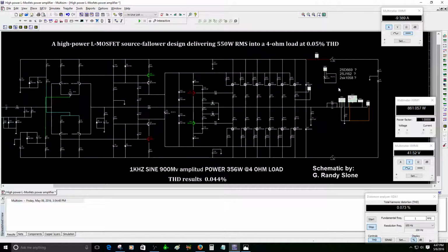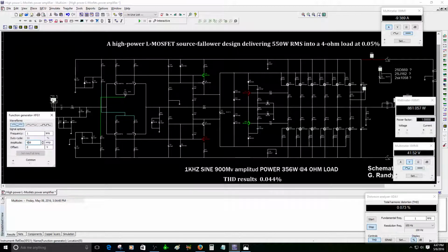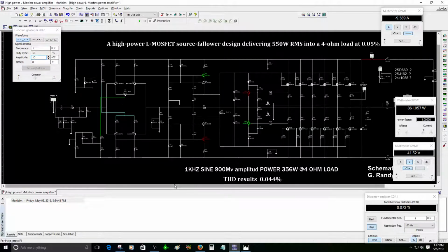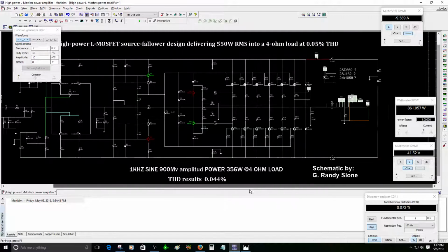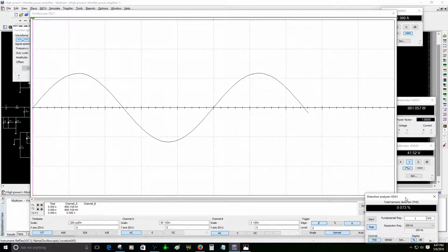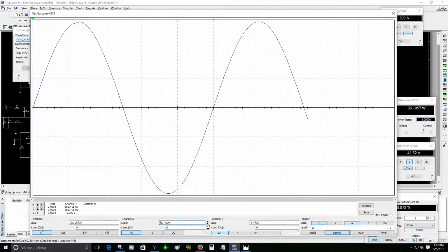So yeah, this is a really interesting circuit. I like this one here. Alright, so I will call this one successfully simulated. I think it's correct. One sample, let me test. I always do that. I'm going to test the lowest distortion possible. I'm going to change the amplitude of the input sine wave to a 10 millivolt sine wave, just to see how much lower distortion I can get from the total harmonic distortion window. I need to see that.